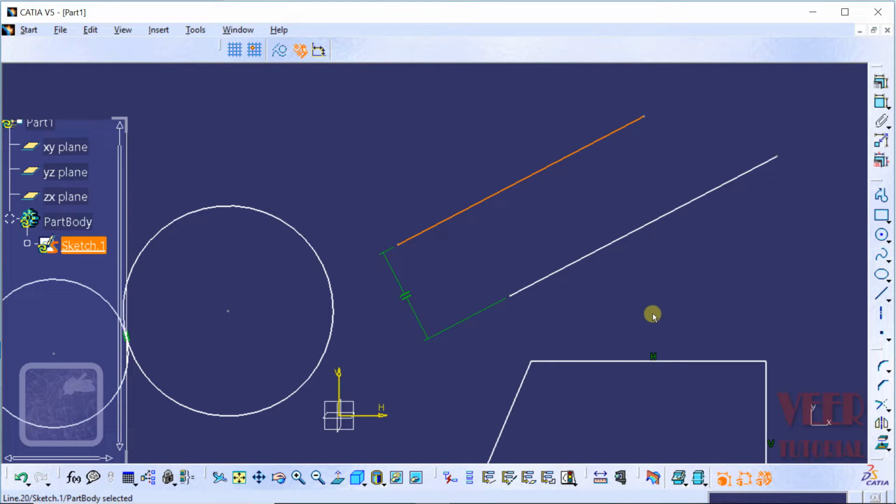Similarly, we can also make lines tangent. We can insert the symmetry by using the automatic constraint. So automatic constraint is really important because it saves our time. Instead of inserting the constraint manually, we can use this automatic option to reduce our time of sketching. So when we cover some more examples of drawing the sketches, we will learn about these constraints in more depth.